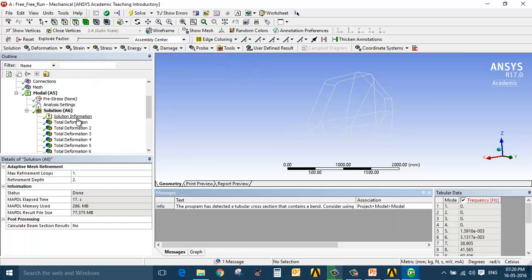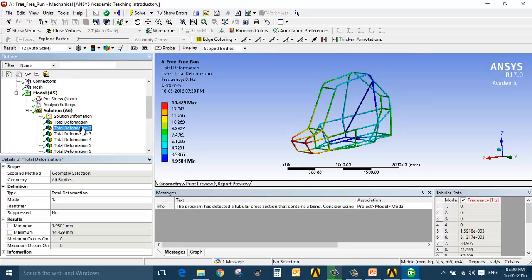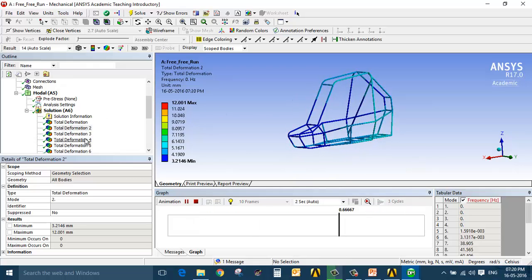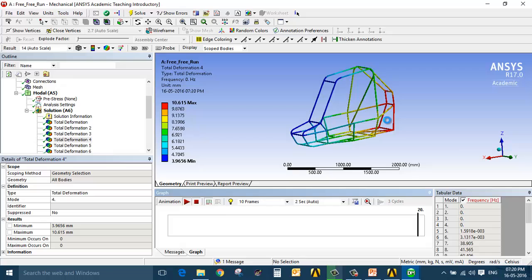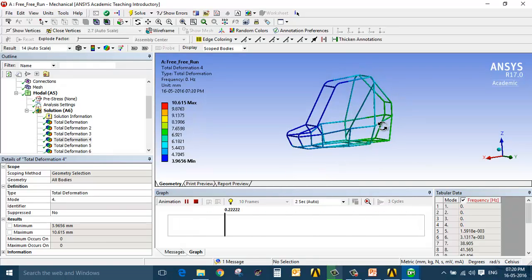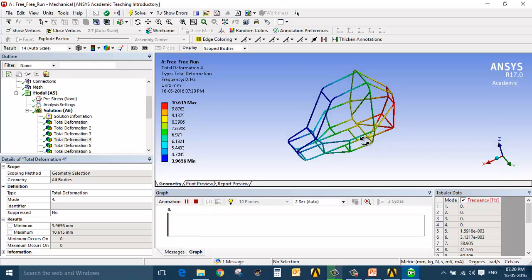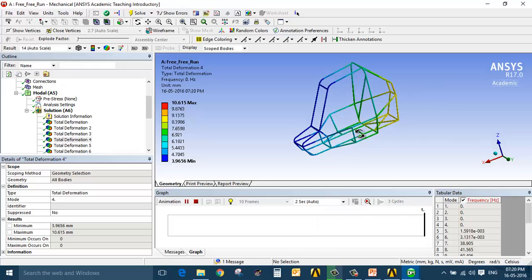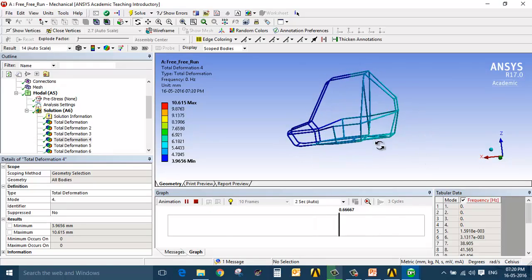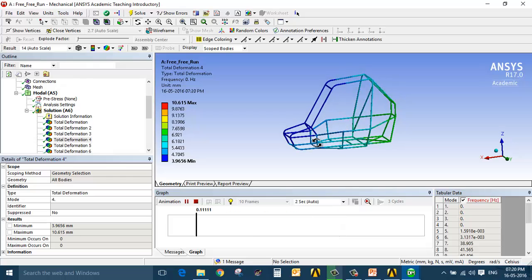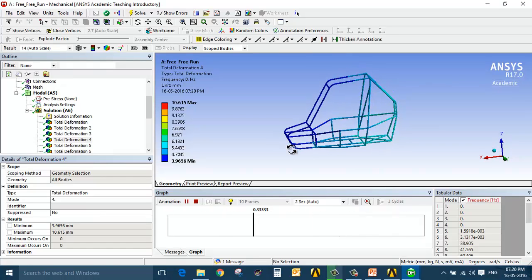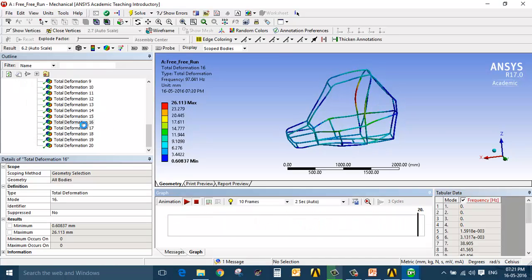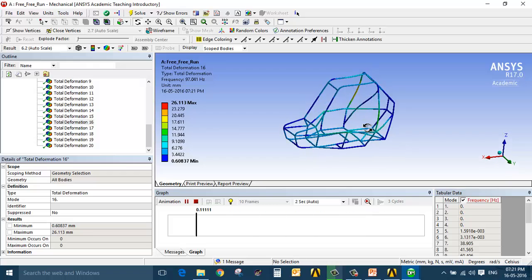So now you can see the total deformation plot on different sections. My entire model is vibrating now. So my entire roll cage is connected. So I can proceed for the static analysis using different loading conditions. That is the most important part before starting any analysis, to check whether my entire geometry is properly connected or not. If I see any geometry or any deformation shape, you can see the entire geometry is properly connected. So this looks fine.